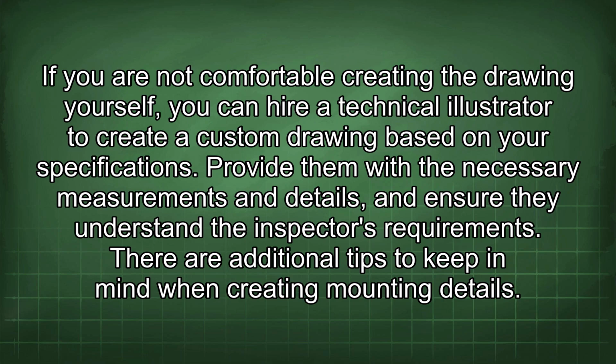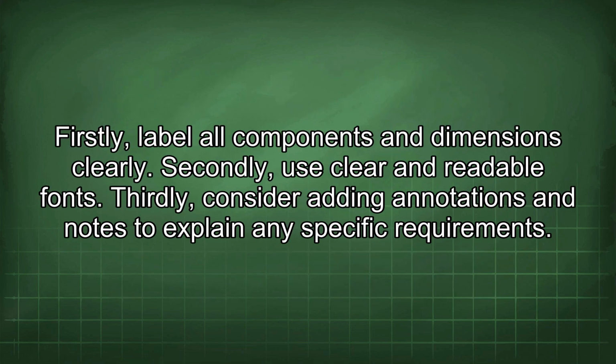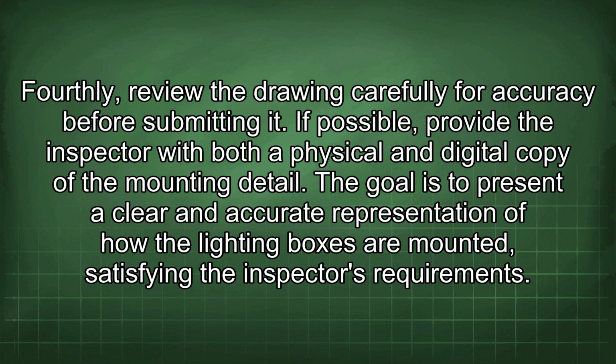There are additional tips to keep in mind when creating mounting details. Firstly, label all components and dimensions clearly. Secondly, use clear and readable fonts. Thirdly, consider adding annotations and notes to explain any specific requirements. Fourthly, review the drawing carefully for accuracy before submitting it. If possible, provide the inspector with both a physical and digital copy of the mounting detail.